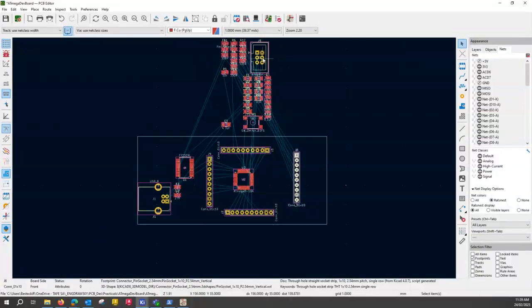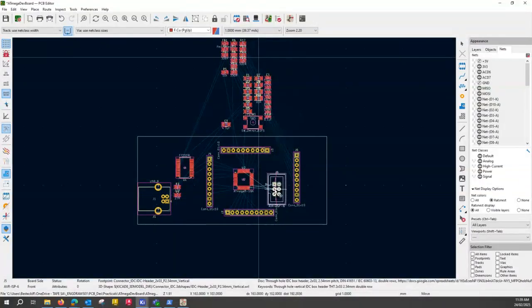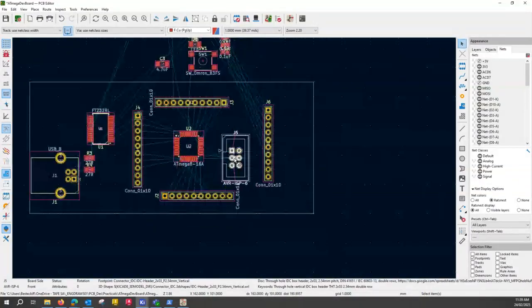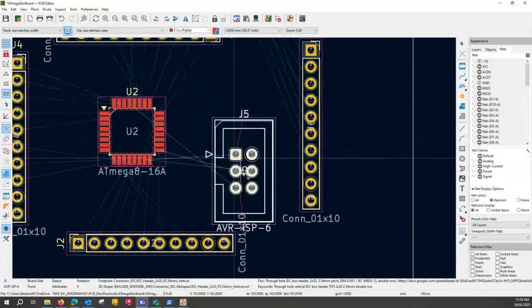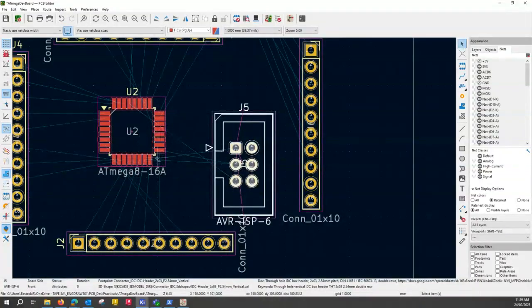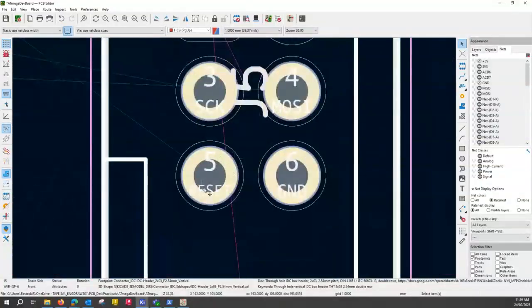And then we've got the programming connector. That's a big one, so I'll move this one. Now, if we zoom in, majority of pins connect to the bottom pins right there. There's one which comes right across there, and the one which comes across is a reset pin. Reset is the least important pin. We're going to wire it absolutely last.